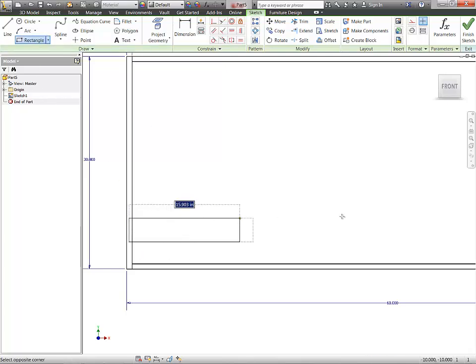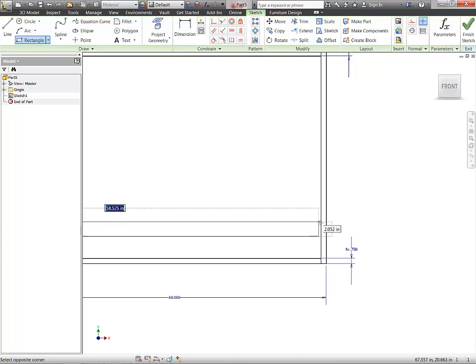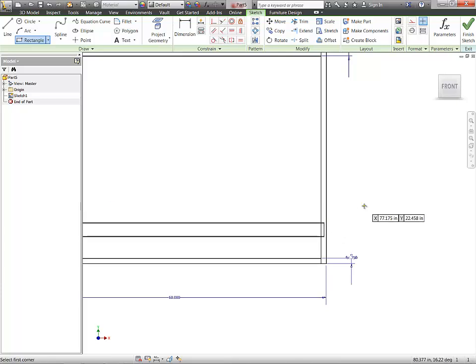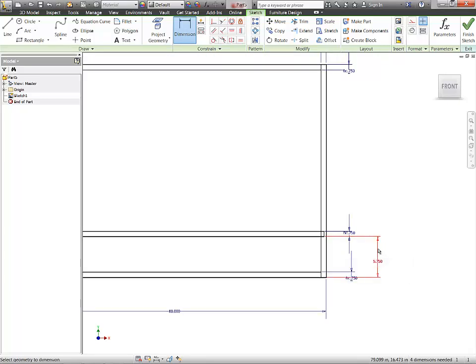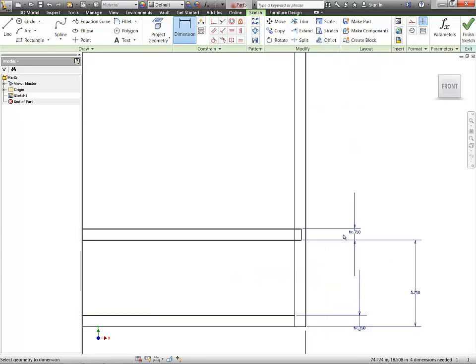And we have no dado at the moment, so what I'll do is I'll just create the rectangle that goes through the side pieces, add a couple dimensions that I want, so they'll equal 3/4 of an inch, and whatever the opening that I'm looking for at this moment in time. So 5 3/4 of an inch. Now, these dimensions will control the item later on.